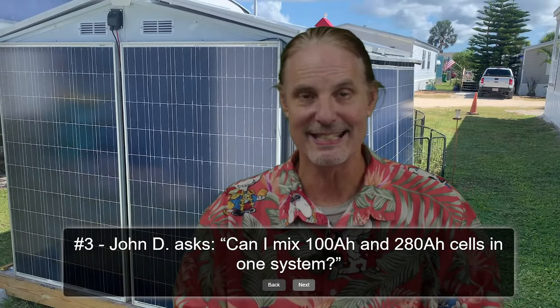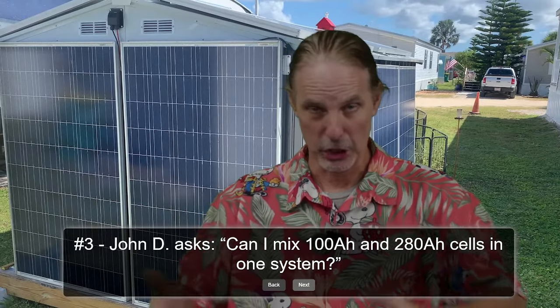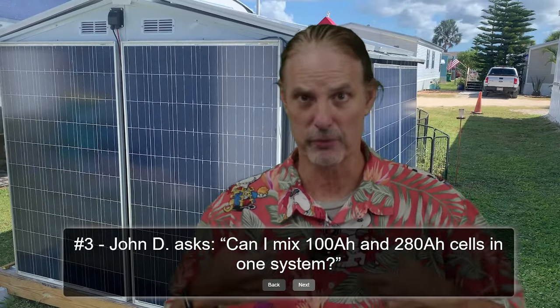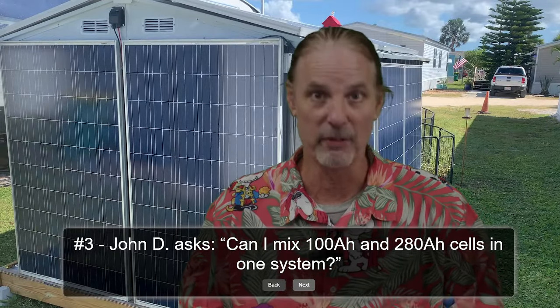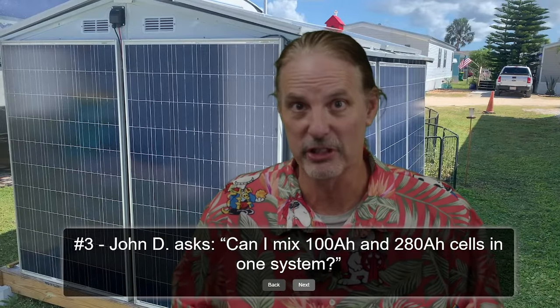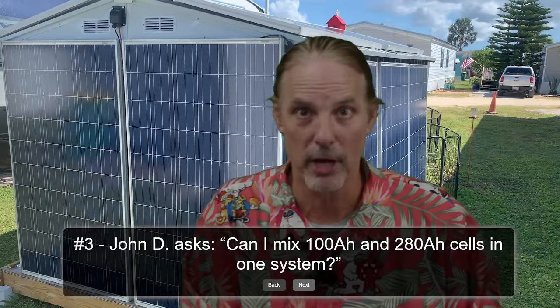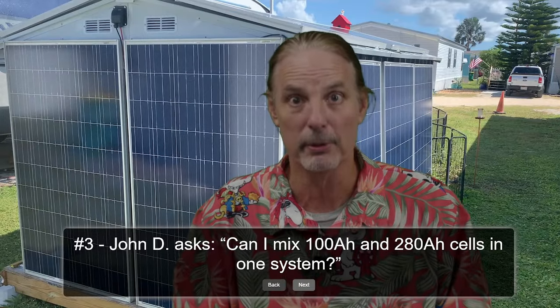It would be very easy to have a bank of 10 batteries get a huge influx from a brand new battery that gets pulled, with all 10 of them pulling on it. If those 10 batteries are low voltage, say 52 volts, and the new battery you're hooking up is fully charged at 56 volts, and you flip it on, you could have 10 batteries all try to pull power from that one large battery, and it could easily cause it problems if it's not properly fused.